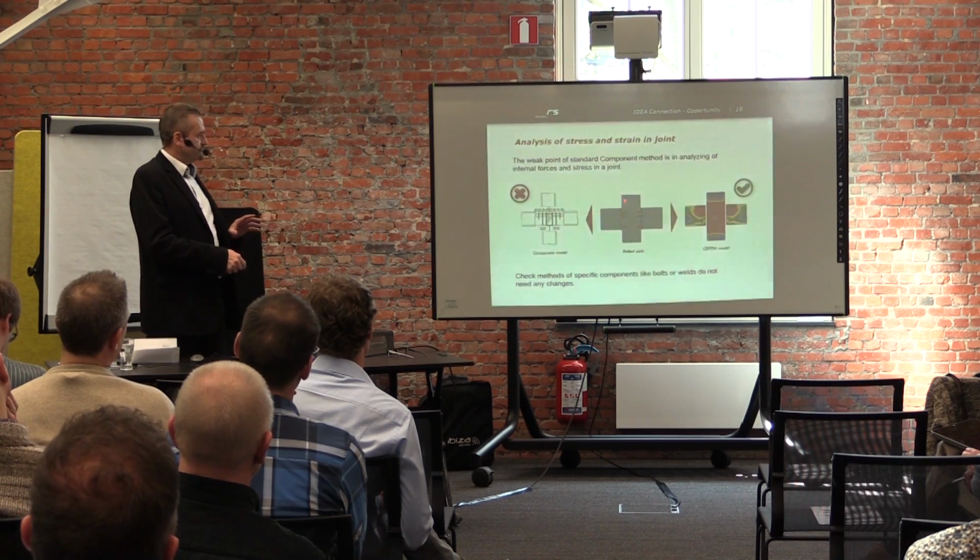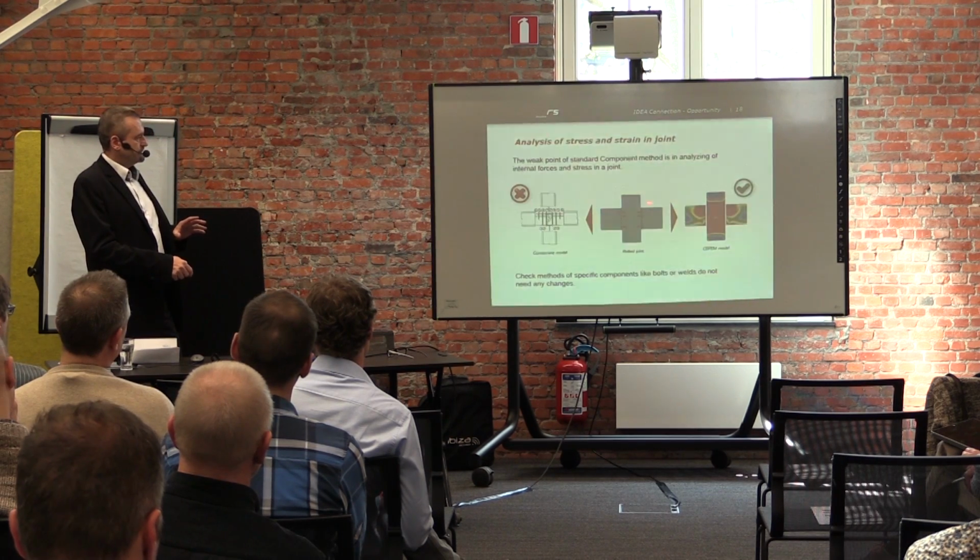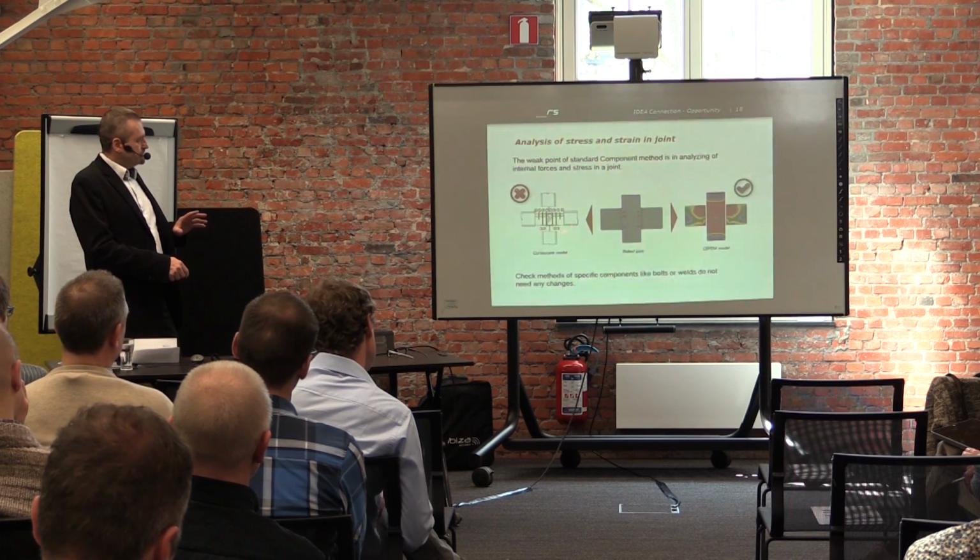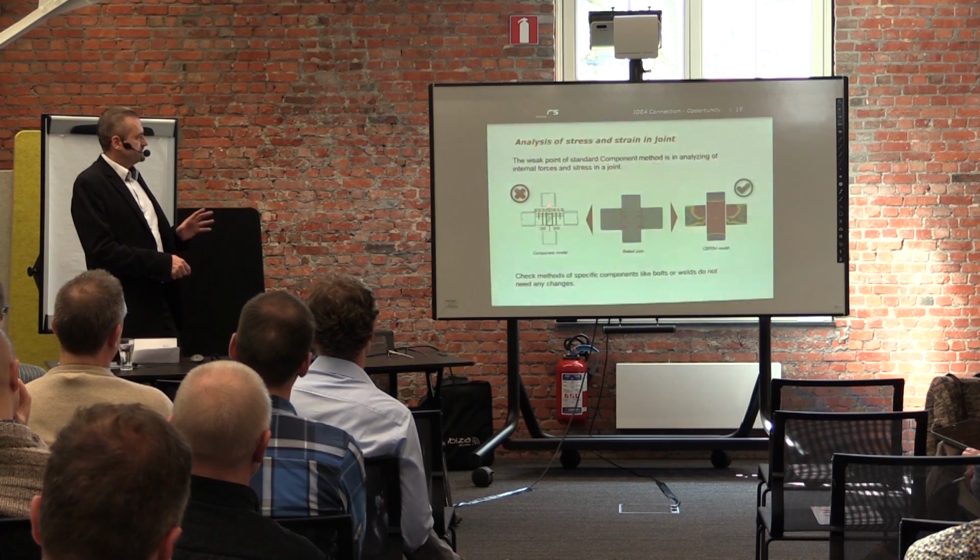In fact, for each topology of joint, somebody must derive this model. With this model, you calculate internal forces, and then you use specific checks for bolts, for welds, for each component. And this is the reason why the component method is not really general. It is suitable only for typical connections.